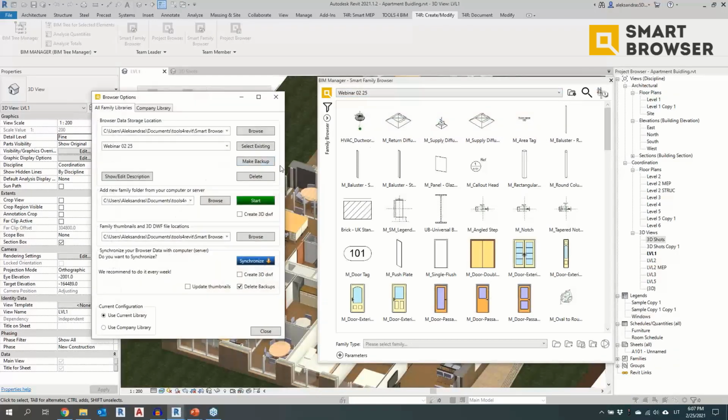How those libraries look is that you just dedicate a specific space where an XML file will be stored, and into that XML file, information will be loaded, and you choose from which folders families should be taken, and information from those families should be loaded into that XML. So elements stay in their respective folders. You only get information about them through the XML.